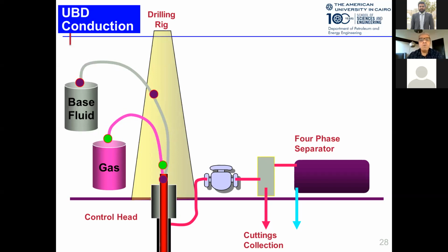Depending on the amount of gas, we lighten the fluid, or reduce the density of the injected fluid, for the purpose of lifting, cutting, cooling the system, and different reasons. These two fluids are mixed together in different ratios, and we control the gas to control the density, and at the end to control the hydrostatic pressure.